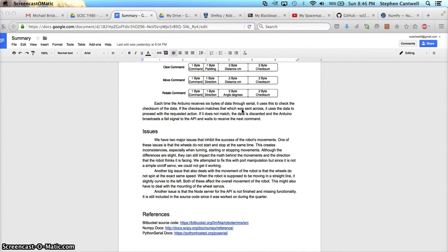We tried to change the code to write simultaneously to all of the pins on the Arduino, but weren't successful. You can try to go down that route as well. It was towards the end of the semester, and we were not able to put everything together. The other issue, and I'm not sure if this is quite the issue or not, but it's a guess, is that the movement of the wheels, thus the power going to the two wheels, is different, so that one servo is slower than the other. Now, I'm not sure if that's an issue, but we wrote it here as a possible issue.